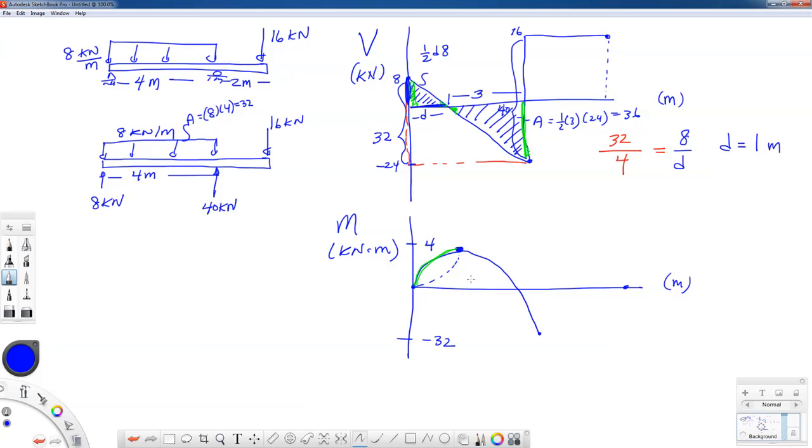I want to point out that if we had a triangular distributed load, you could do this to find the concavity of the shear force. You can even do this sort of approach if you had a parabolic curve and you want to put a cubic moment equation and sketch it out. Same sort of approach is valid there as well. Alright, so it goes in this curvature.